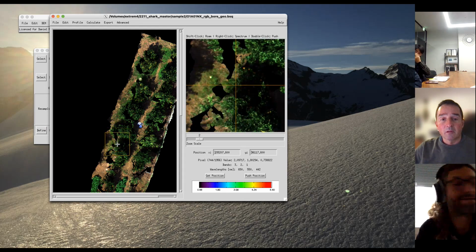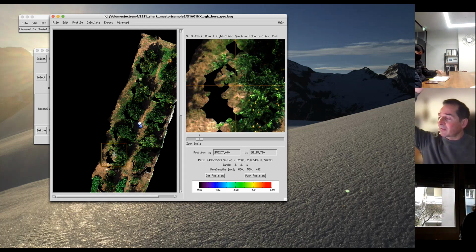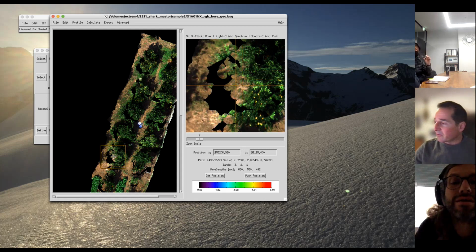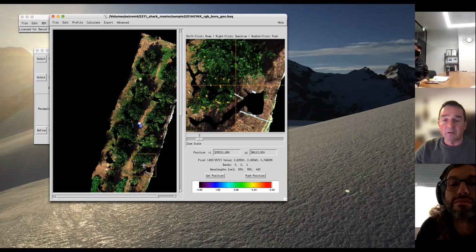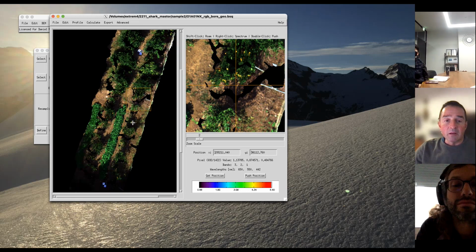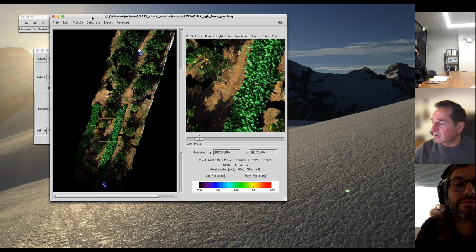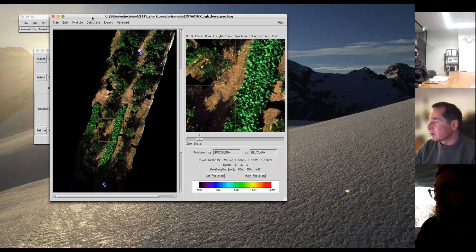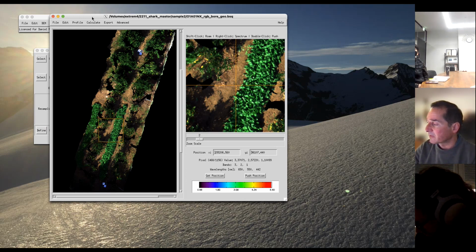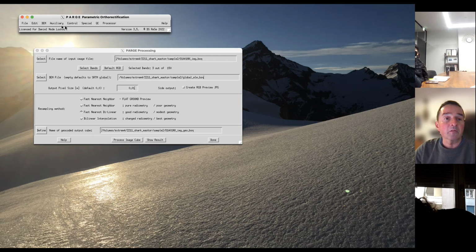You see these gaps, because the tree is elevated and it's a straight line of the surface model. So I think it doesn't make much sense to use this digital surface model here. I think one has to go for the flat ground. So that's why I chose to use a flat or a digital terrain model. While I only had this global elevation model, I guess you will have a better one available somewhere. So a digital terrain model from Korea must be available somewhere. You could search for such a one and use it for the processing.